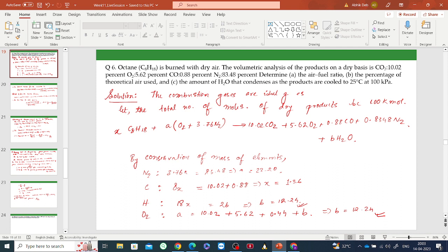For the formation? That is, if carbon and oxygen are reacting to form carbon dioxide, then what will be the enthalpy for that? This can be determined: if carbon and oxygen react to form carbon dioxide, there will be a release of 393520 kilojoule of heat per kilomole of the carbon dioxide produced. Since it is heat released, this will be denoted as minus. So minus 393520 kilojoule per kilomole is the enthalpy of formation of carbon dioxide